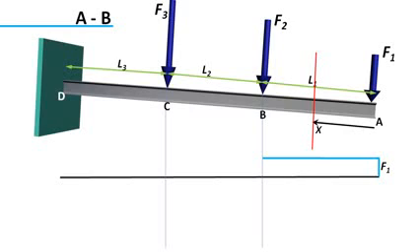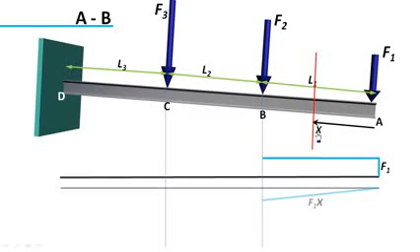But force balance alone does not guarantee equilibrium of the section. There is an external moment on the section. So a bending moment will be induced in the section, in order to balance the external moment. Since the value of external moment is F into x, bending moment will vary linearly.